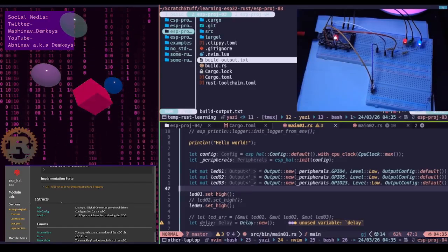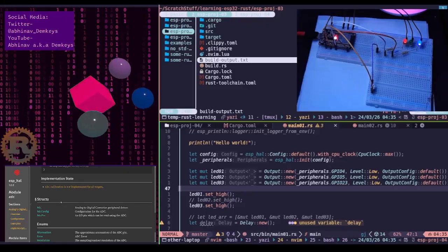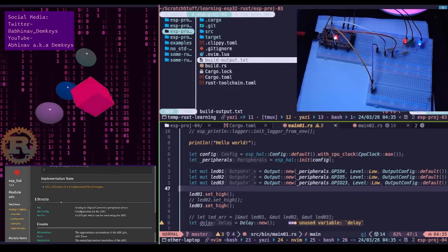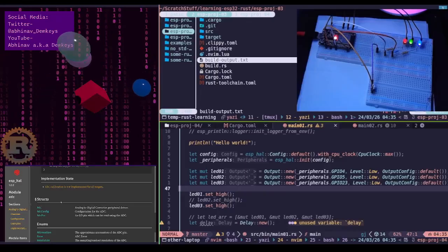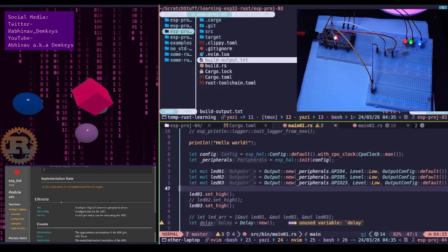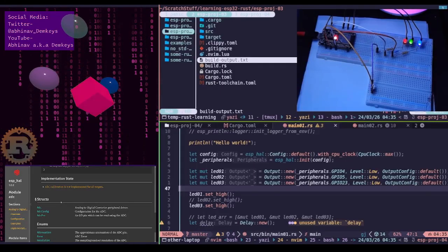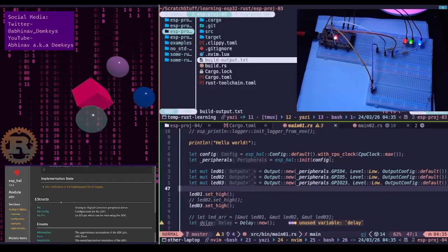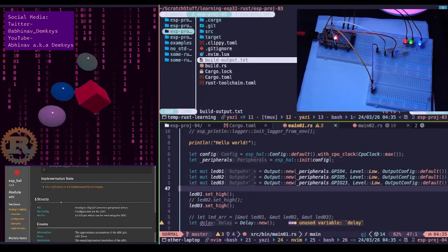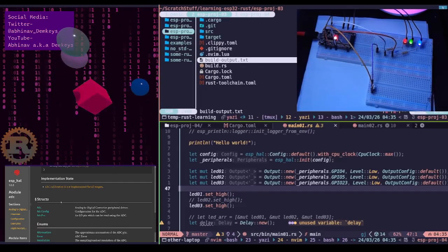What about current? This is a crucial point for hobby electronics. A voltage divider is for signals, not for power. Because the ESP32 ADC pin has high impedance, meaning it's like a very, very tiny straw. It draws almost zero current. It just looks at the voltage level.